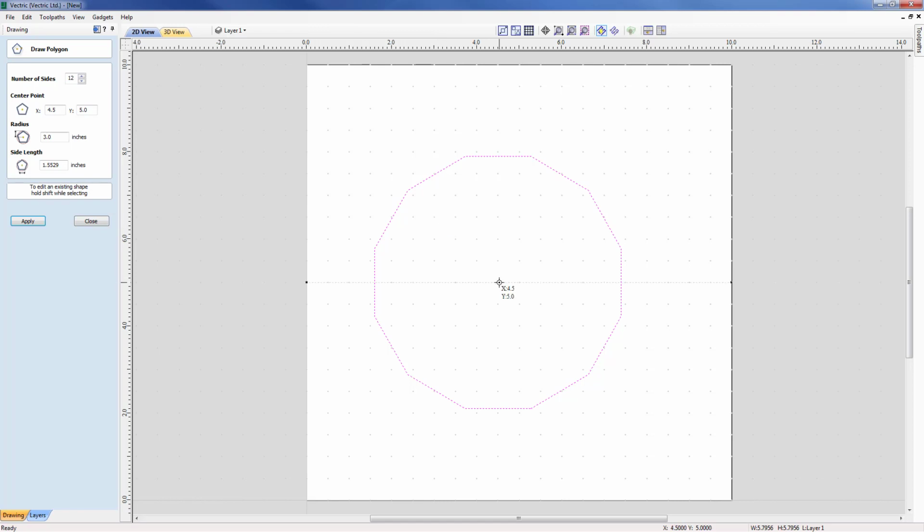Similarly, I specify that with just a radius. I can do the same by specifying, say, 12D, and you can see that I've given it a diameter of 12. So as well as specifying just the diameter or radius, we can also add in the number of sides we want. So if I'm going to click now and start scaling up, we can see that we're getting 12 sides, but I maybe want to specify this with maybe just 8 sides.